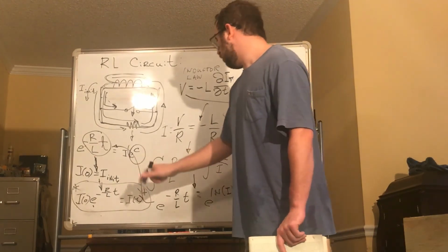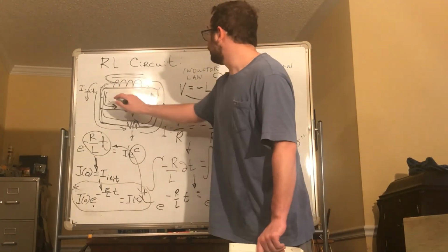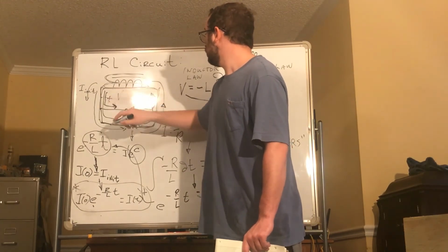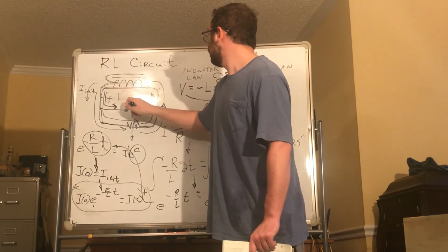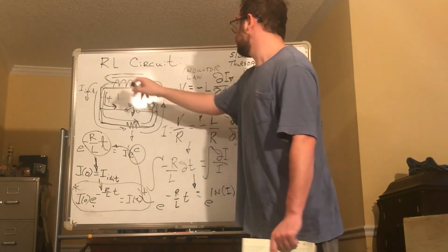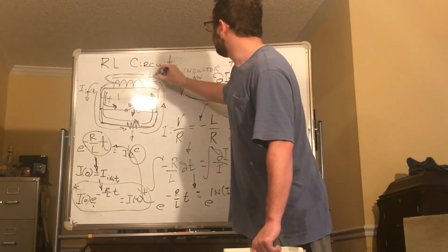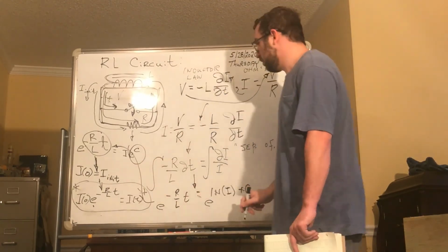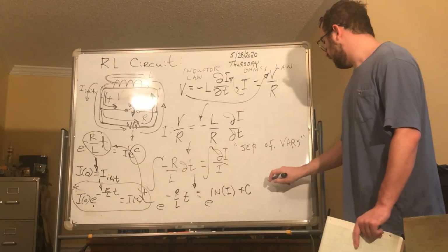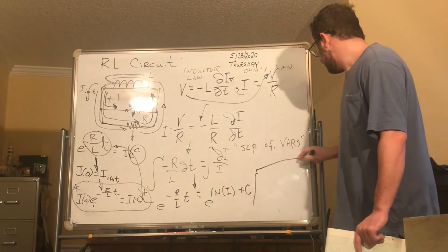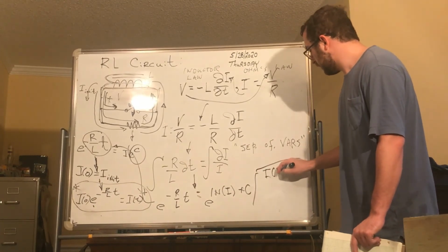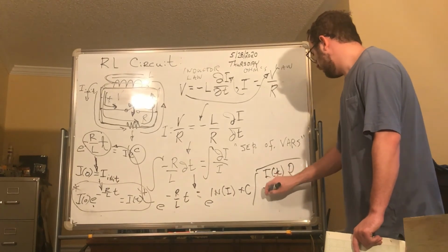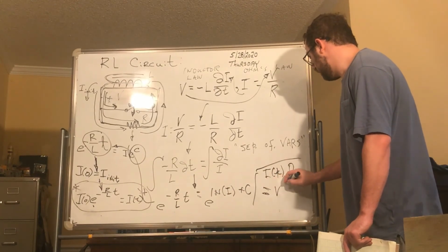Now, you may wonder, what is the voltage between here, V, when this is opened and forces it through the resistance? Again, this is L and that's R. Well, we can use Ohm's law explicitly, and so it's worth noting we can take the function of I of t that we just got and multiply by R, and then that would equal V of t.